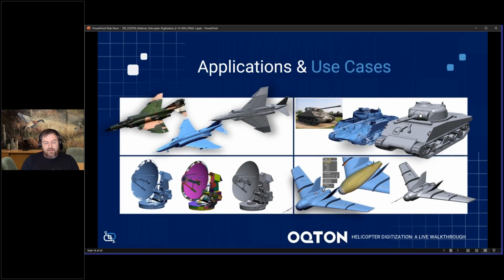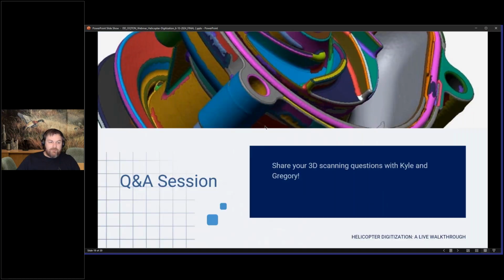And this is what I'm talking about when we talk about time savings. If all this modeling is a simple block with extruded features and some holes, yeah, DX is going to save me a little bit of time. But when you model this entire thing, it's going to exponentially save time being able to model directly on the scan data. And it's essentially extracting the dimensions for you from the scan data.